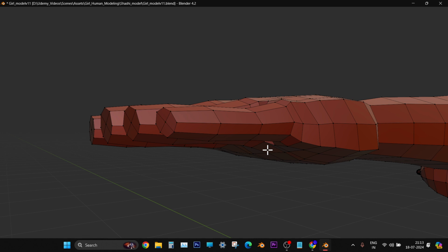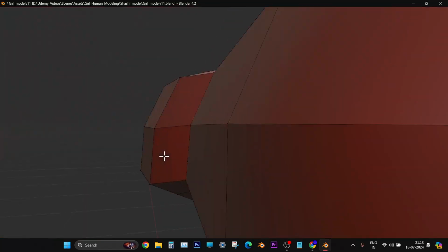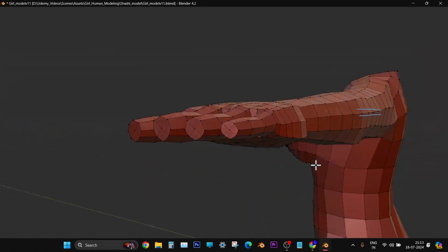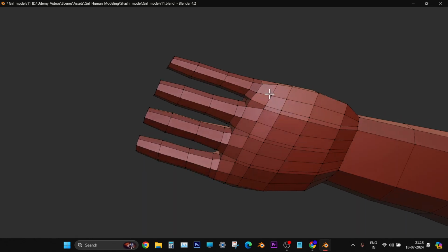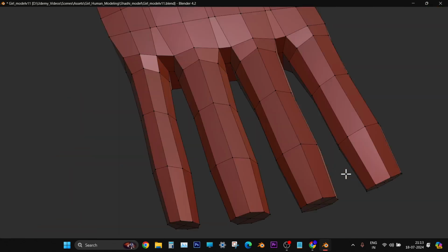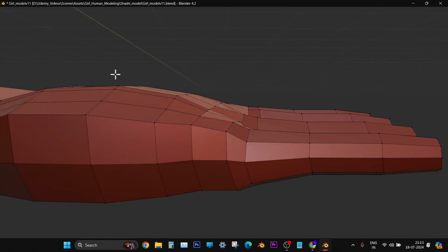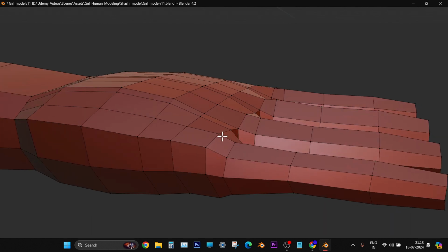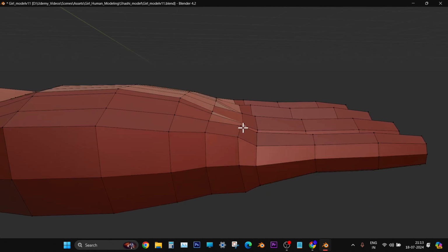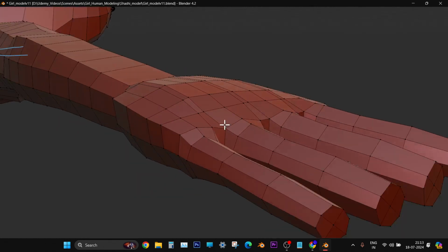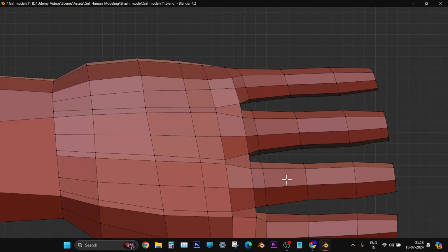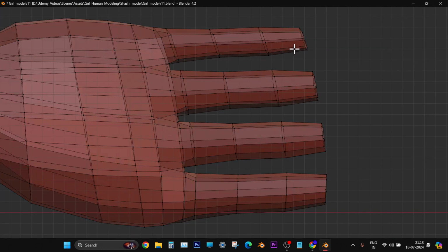It won't look like an organic shape. So here itself we should not decide whether to move these vertices wherever they are. So let's leave it here with whatever it is now. Let's not go into the details of these shapes. These things we have to make flat, but using the sculpt we can do that, or using the proportional editing at least we can do that, but later only, not now. So right now we are going to focus on the fingers.